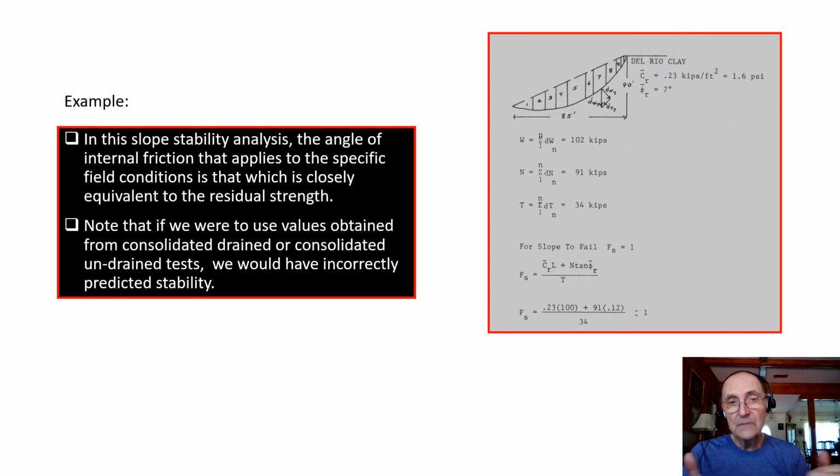Also note that if we were to use values obtained from your typical consolidated drained or consolidated undrained tests, we would have incorrectly predicted the stability of the slope.